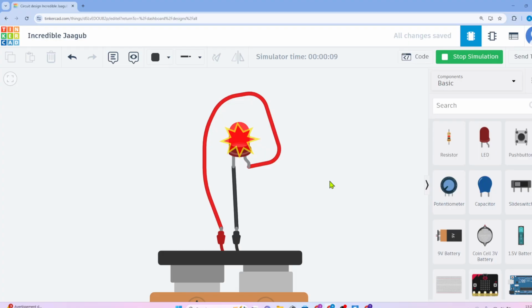As you can see, the LED is turned on, but there is something more dangerous here. There is a warning in the platform. This is why it is also important to use a platform simulation to see the dangers. We see that there is a warning on the circuit. Why? It is probably because we didn't use a resistor to protect or to limit the current on our LED.